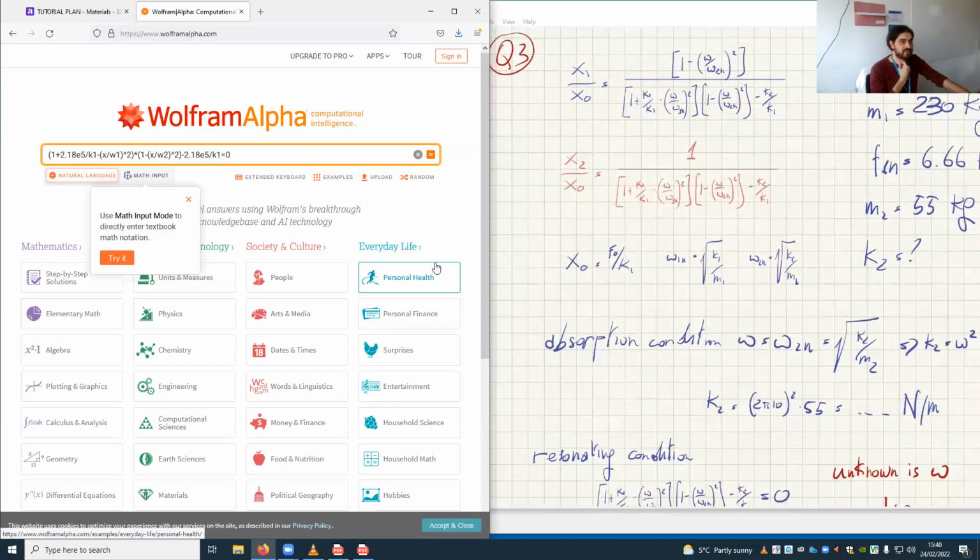Oh, see, we can do this in hertz, because these are all ratios. If I put F1n and F2n instead of omega 1n, I get X in hertz rather than in radians per second. Is it clear? Can you see that? I'm not doing any kind of wild magic. Instead of omega 1, I put 6.66 in hertz. And here I put 10 because I know that omega 2n was equal to the old omega.